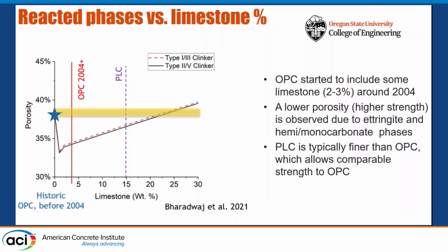Now, we had it without limestone. Now, the thing is that, as I said, at 15%, you also have diluted your system, so you have a little bit less CSH, but we want to get very similar strength from these 1L cements. So in order to compensate for that decrease in that beneficial CSH, we basically intergrind the limestone with cement a little bit finer, and that is intended to give you the equivalent strength as before.